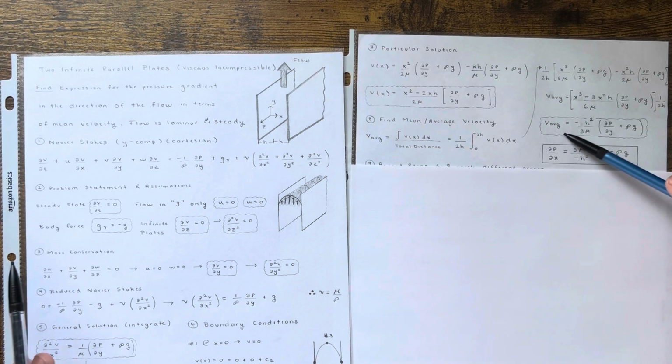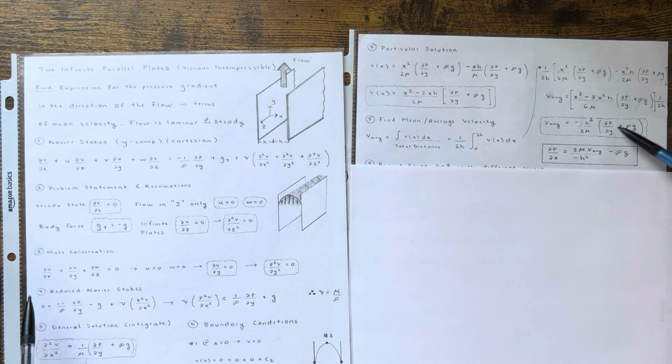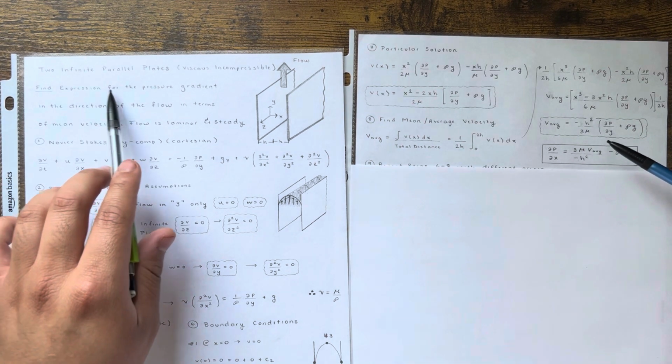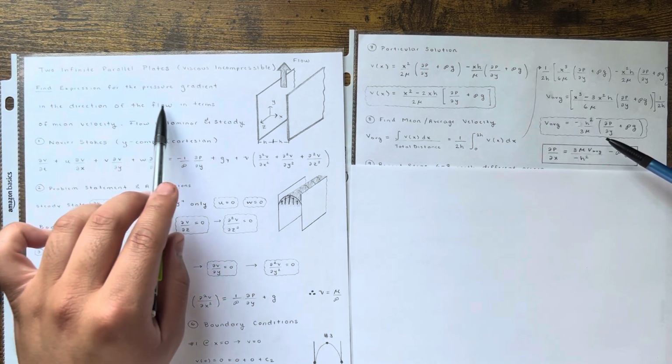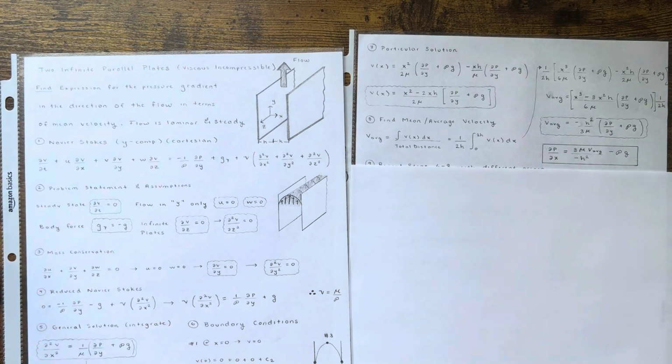So now this is the average velocity. And now all I need to do is solve for this delta p over delta y, okay? Isolate it, and that's your answer. That's finding the expression for the pressure gradient in the direction of the flow in terms of mean velocity. And boom, we found it. Now that's the answer. You can stop the video right here if you want, no big deal,